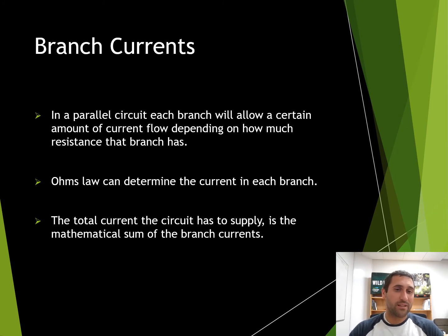Branch circuits, this is what we're talking about when we're talking about parallel circuits, and each branch will allow a certain amount of current to flow depending on the draw, or how much resistance that branch has. And that's what we're talking about when we talk about draw.